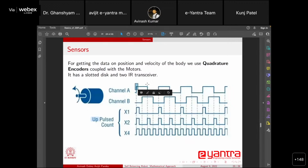An event is detected at this point and an event at this point. So from one channel we can have two events. If there are two channels, we can have a total of 4 events for one slot pass. Suppose there are 360 slots on the rotating disk. We can then have a resolution of 1 degree per slot, or half a degree per slot, or 2.5 degrees per slot.